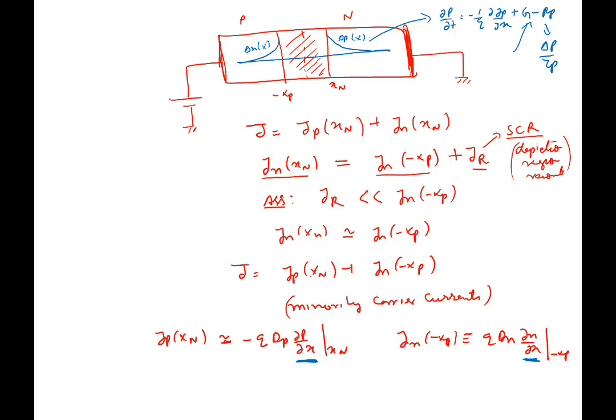If there is light shining, you put G there, and then you get a solar cell kind of operation. If there is no light shining, then you put G equal to 0. We are talking about steady state, so you put the time derivative equal to 0. We already have an expression for how Jp goes in the N-type region; Jp in general is diffusive. So you do that and solve a second order differential equation, which we have done, and you get the variation of delta Px.